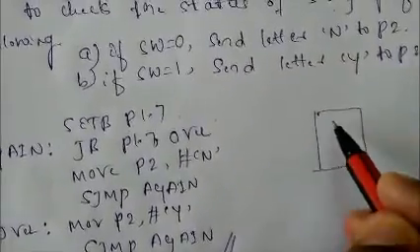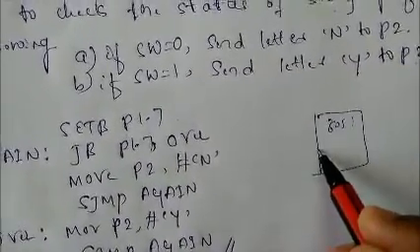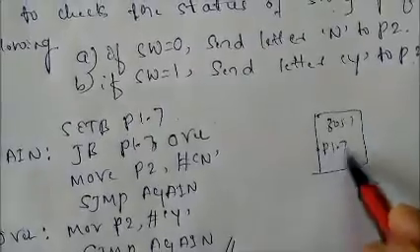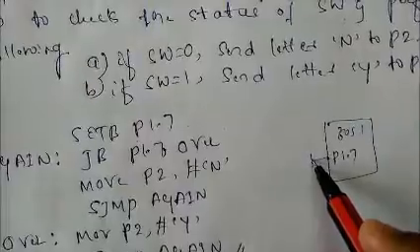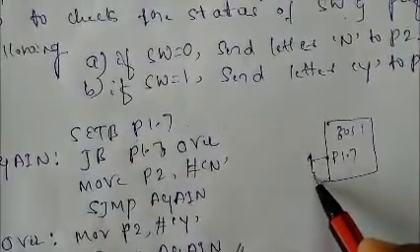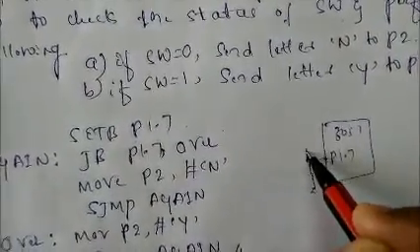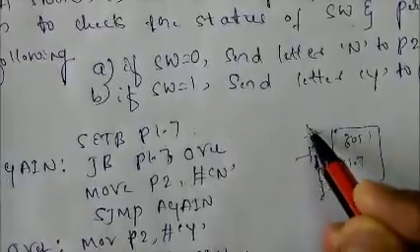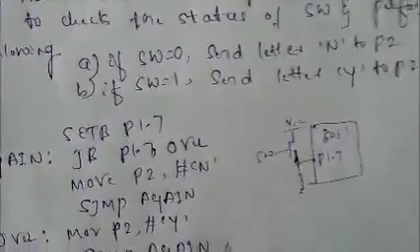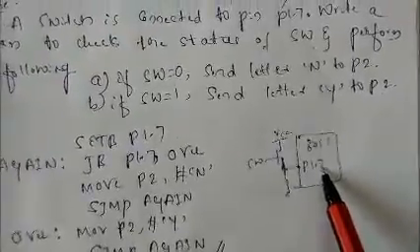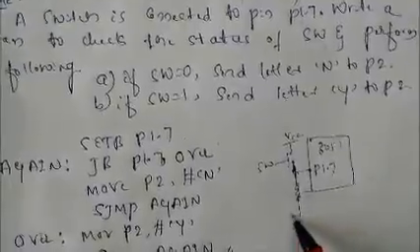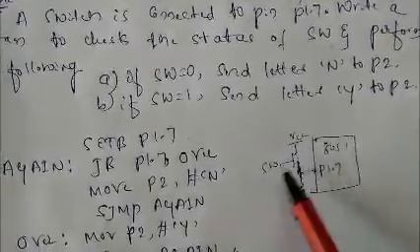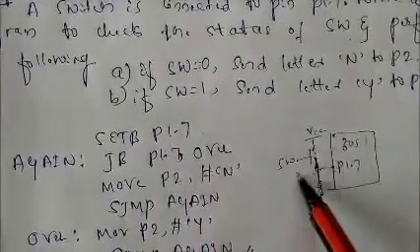This is your 8051. Is it clear? So this bit, if I consider P1.7 here, here I connected one switch. Here at this point, something like registers will be there. So this way P1.7 is connected to your switch, I will show one register here, and this is your ground position. I will show one switch. Is it clear? So SETB means I am making it an input port.